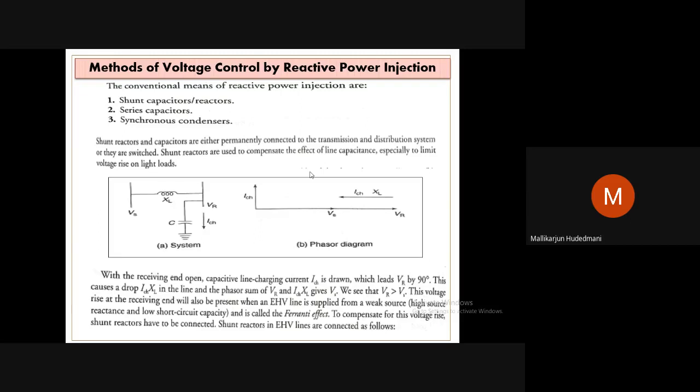When a transmission line is delivering a highly inductive load, quite naturally the lagging VAR demands compensation. Suddenly the load is withdrawn or declining. The compensation being applied to the system then leads ahead. Again, that affects the voltage profile of the system, so it needs to be absorbed or suitably controlled.